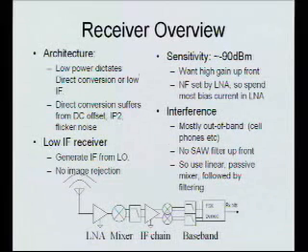That's a good question. It really boils down mostly to your ADC. There are two reasons to go all the way to baseband rather than just doing it at an IF. One is that you have to have a faster sampling rate on your ADC if you're at an IF. For example, if I have a 2 megahertz IF, then my sample rate has to be at least 4 megahertz to meet basic requirements. So that's more expensive than an ADC running at 100 kilohertz.